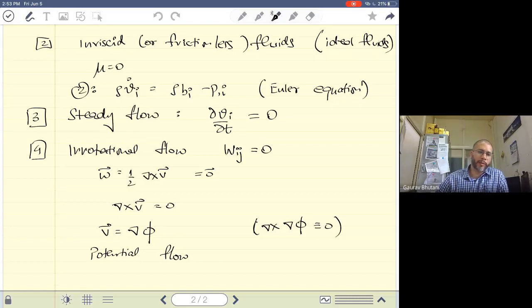So if you have the phi scalar field changing, so it's not a homogeneous field, then that would mean that there is some gradient of phi, and that is what velocity is at any given point. Okay, so there's a potential phi, and the difference in that phi potential causes a velocity to exist at any given point. So this is called potential flow.